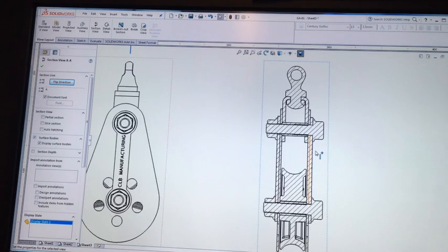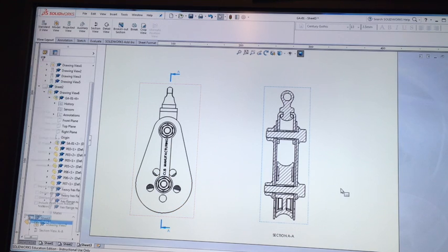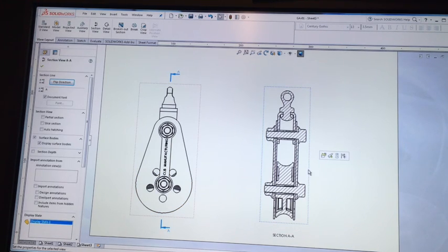All right, so the section view, how that works, it's cut a line through the model, and it's basically showing all the parts here. And if I turn hatching on, they'll be hatched in different directions. If you press slice section, it'll just hide anything that isn't on that line that you've cut through.